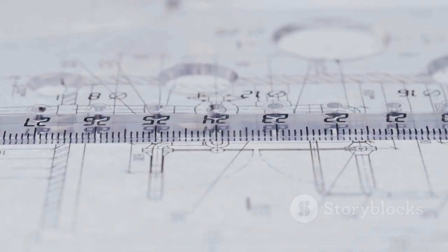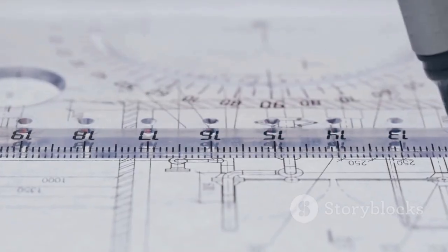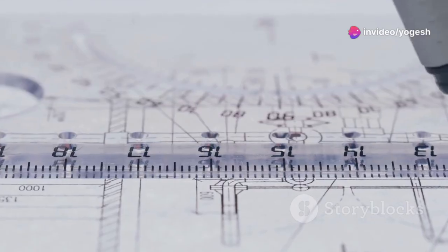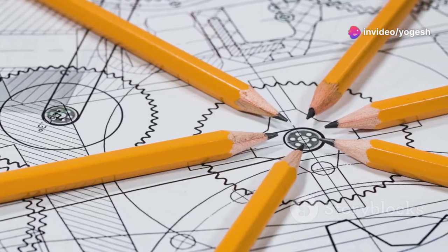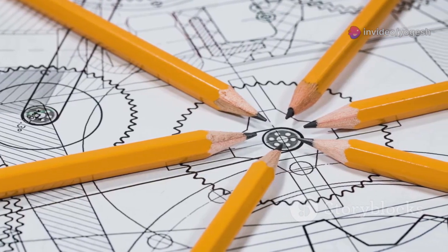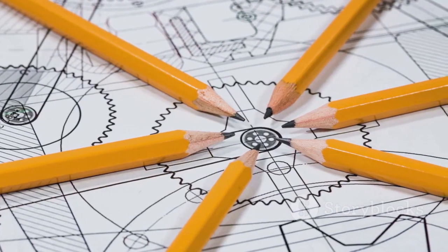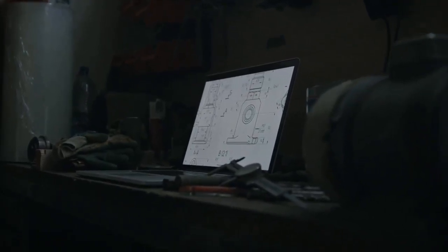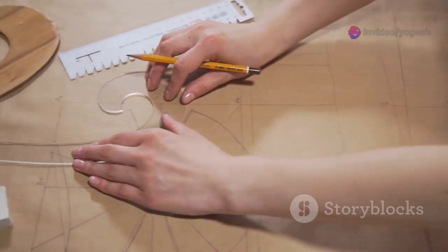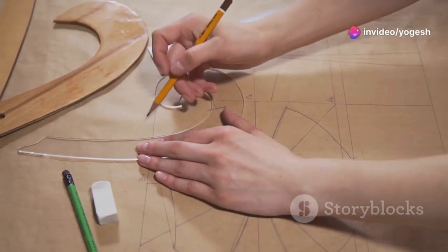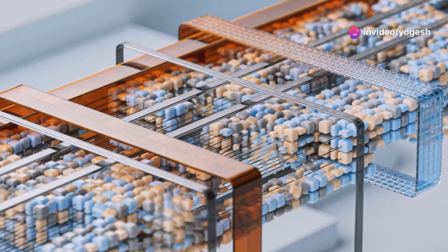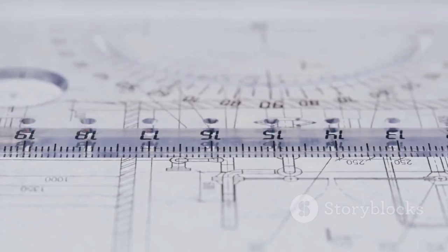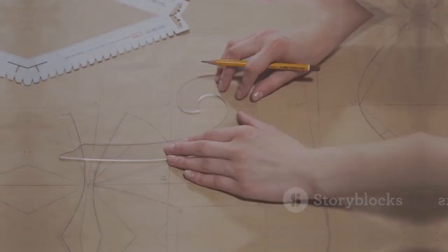To reveal hidden interiors, use a cutting plane line. Bold, with a long dash and 2 short dashes. Ends bend at 90 degrees with large arrowheads and section labels like A-A. Place the line through features you want to show, using offsets if needed. The resulting section view is drawn as if the cut were a single, flat plane. Cutting plane lines make complex interiors easy to understand. Use them to show what hidden lines can't.